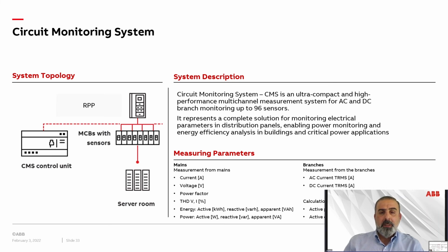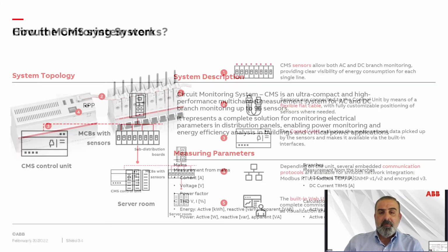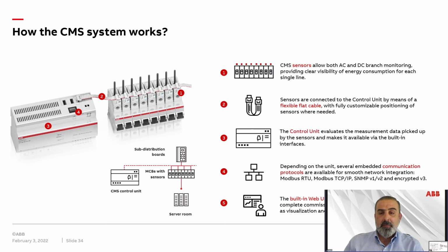Components of the branch monitoring systems are very well streamlined. One control unit that connects to all sensors in the system. CT sensors will be installed on the outgoing branches dedicated to measurement of the energy consumption of each circuit. Additional flat cable to connect all the CT sensors to the control unit. I/O units that are programmable and can be connected to the system.